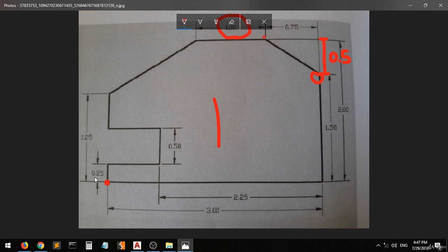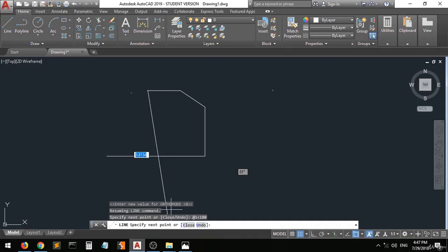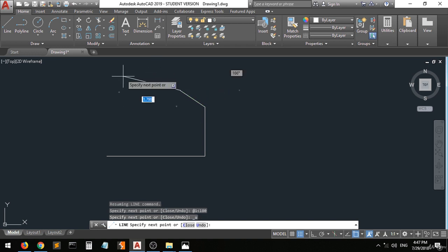Vertically with 0.25. But first of all, let's do this again in the coordinate entry. So we have put this in the polar entry. Let's do Ctrl Z for the undo. Now let's use the coordinate entry. You have to type what is the length or what is the x coordinate of this line. It will be 1 slash, in the y-axis we're not moving, so we will type 0 and now enter.